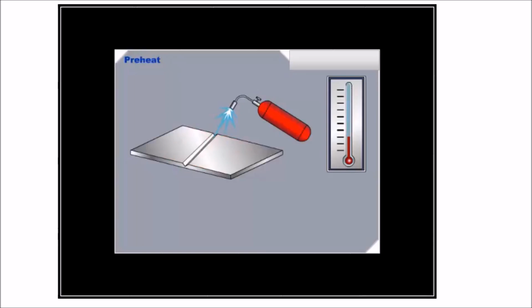In some cases, depending on alloy content, martensite may be formed. However, when preheat is included, the heat-affected zone is wider and the resulting hardness is significantly lower due to the slower cooling rate, which allows for the formation of ferrite, pearlite, and possibly bainite instead of martensite.